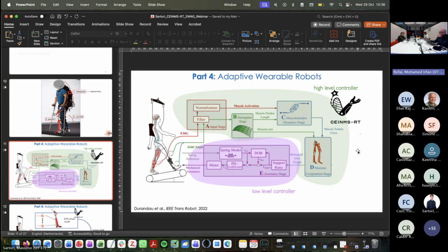The middle-level stage is soft real-time, because CEINMS essentially communicates with EtherCAT through plugins, and the plugins work using UDP or TCP/IP. So the middle level, the CEINMS layer, actually sends data packages through UDP, which means that there will be a variable latency at that stage.